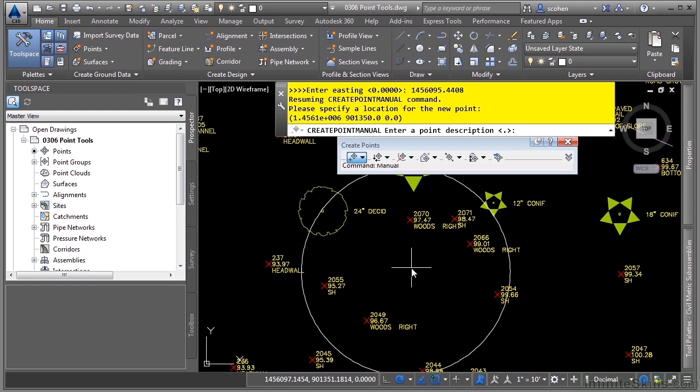This will be a DECID 6. So DECID, that's the raw code that will be mapped to our description key set. And then if we type 6 here, because we're using that parameter 1 that we discussed in the description keys video, you'll see here that automatically it'll actually add the symbol and scale the block based upon the parameter. The elevation we have here is 97.32. Press enter. And as you can see, the block comes in differently and it has the description necessary.